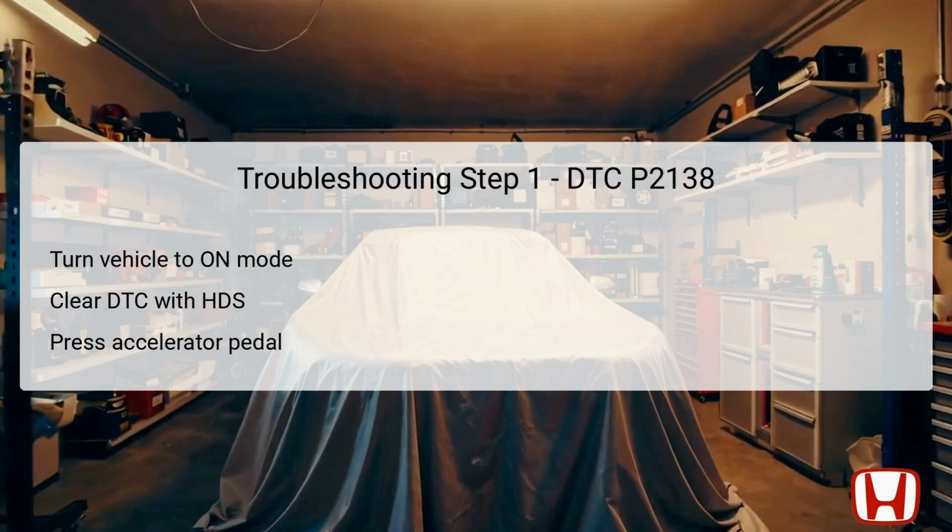In the first troubleshooting step for DTC P2138, it is essential to turn the vehicle to the on mode without starting the engine. This allows the electrical systems and sensors to become active for diagnosis. Next, clear the DTC using the Honda Diagnostic System, HDS, a specialized tool that allows technicians to communicate with the vehicle's onboard systems. After clearing the code, press the accelerator pedal down to the floor fully to ensure that the APP sensors can send their maximum signal output. After performing this action,